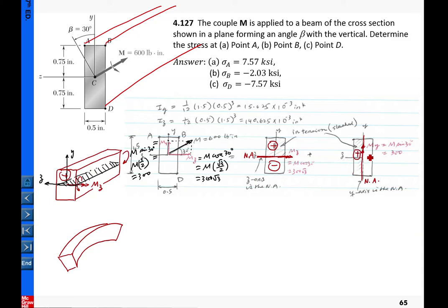The left side will be tension, this will be in compression. So with everything ready, then we can begin to calculate. And for this subsystem, let me use the color, the magnitude of the stress has magnitude equal to, again using our template, M is the moment being applied, so for this case is Mz,